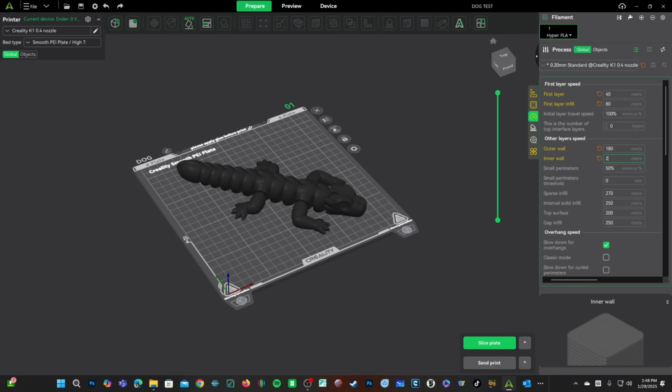However, the slower these speeds, the better the chance of a successful print, avoiding things such as extruder jams, knocking the prints off the print bed, failing your first layer, etc. And the difference between 200 and 250 and 300 is not as much as you think. Generally speaking, being in the 180 to 200 area is a good safe place to be for printing consistently with very few hardware or print failures. I highly recommend, especially to newer users, to lean on slower speeds.